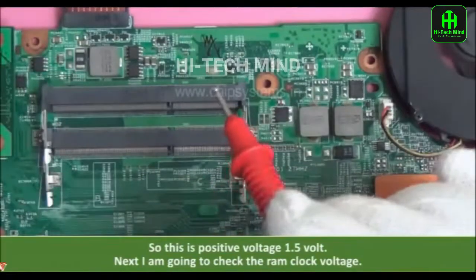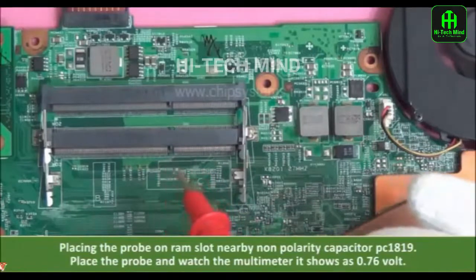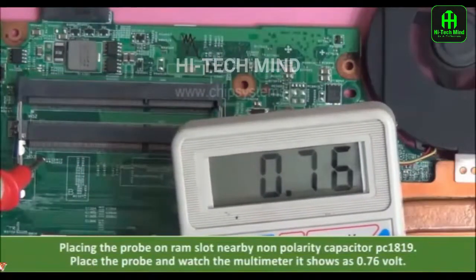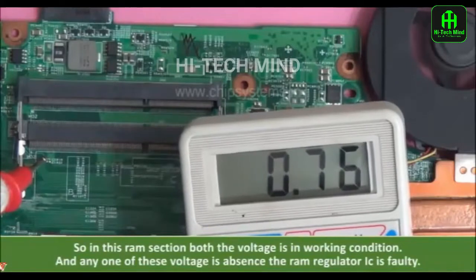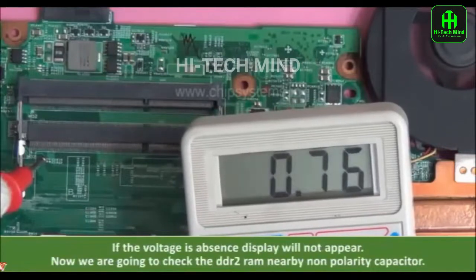Next I am going to check the RAM clock voltage. Placing the probe on the RAM slot nearby any non-polarity capacitor, PC1819. Place the probe and watch the multimeter. It shows 0.76 volt. So in this RAM section, both voltages are in working condition. And if any one of these voltages is absent, the RAM regulator IC is faulty. If the voltage is absent, the display will not appear.